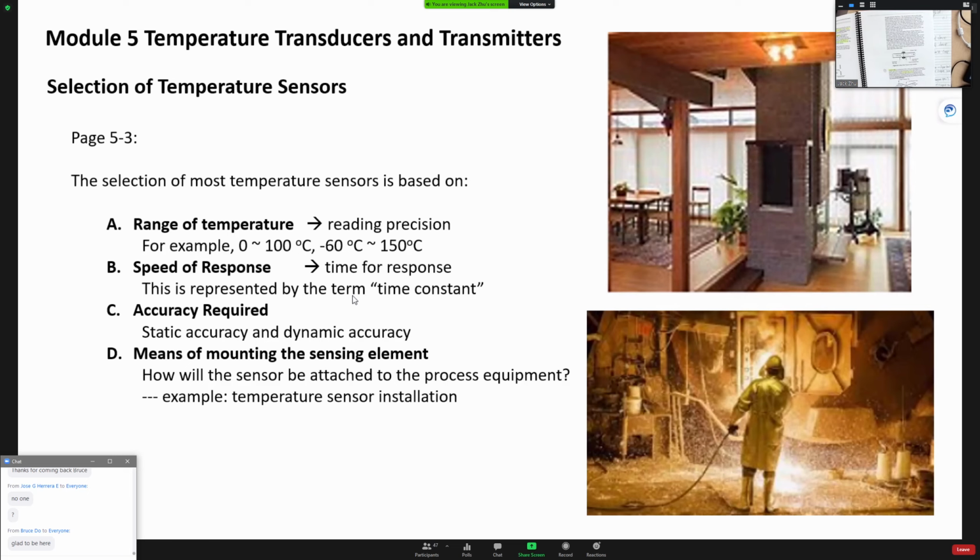So the heat transfer generally takes three different types. One is conduction. Usually with a solid piece of material, you heat one end, and the heat is going to slowly move from one end to the other end. This is considered conduction. Another one is called convection. Convection usually happens in fluids, either water or gas.